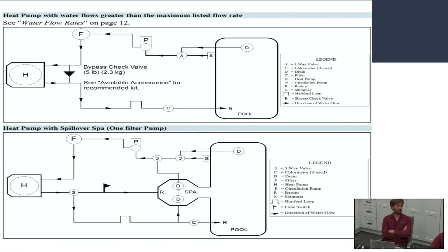It runs constantly. The spa mode is activating. You see all the bubbles coming on in the spa, but it's still pulling from the main drain. The jets got redirected to the spa only, but it's still pulling water from the main pool. So all of the pool's water is trying to circulate, forced through that spa.